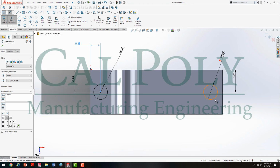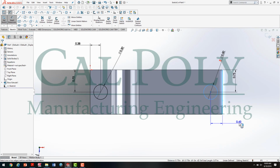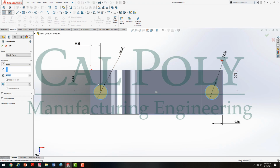At this point, I'm going to click the edge of the circle, the edge of the part, drag down, and type in 0.375. Now I have two fully defined sketch entities, hence the two half-inch circles fully located. At that point, I'm going to hit Exit Sketch.